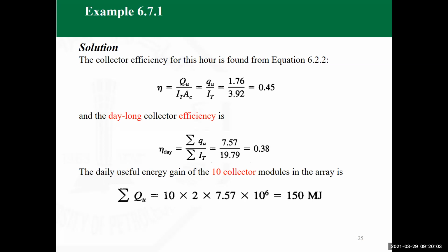But big hotels, 4 and 5 stars, are not doing that. They are doing central heating for the whole hotel. They may have a large electric heater, but mainly because of the higher price of electricity, they go for the cheaper option of having a boiler. The boiler is a heat exchanger. Basically, they burn diesel fuel, and the diesel fuel heats the water, and you take the water in a net of piping system, which is well insulated, to deliver hot water to the rooms.